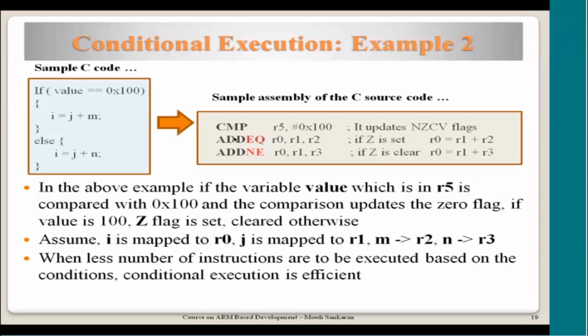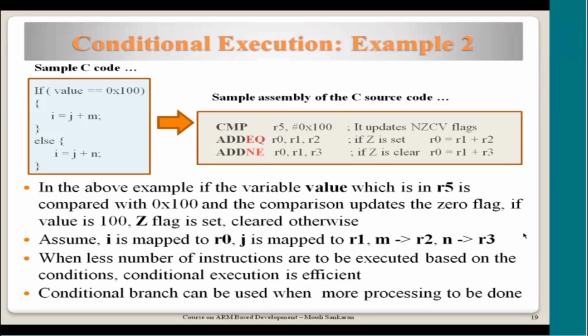So here you have to remember that if you are putting a sequence of instructions which are based on some conditions of CPSR, these instructions should not impact the CPSR value. See, execution of this instruction is controlled by the CPSR, and the decision on whether this instruction can impact the CPSR is based on whether you put S here or not. So you have to make sure that they don't impact the CPSR values because they are not intended here in this particular situation. So you should remember that when you are writing an assembly program, but the compiler may not do that job. Okay.